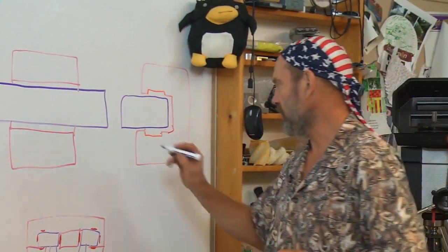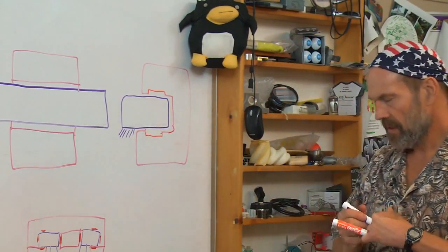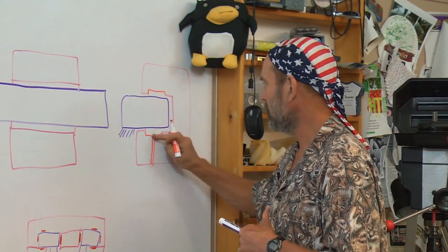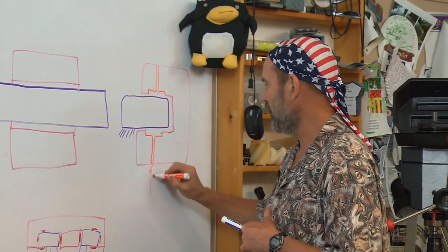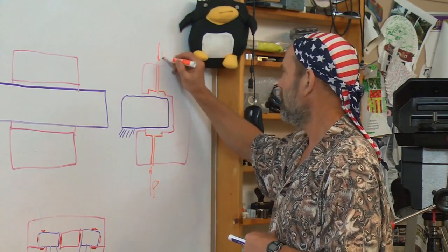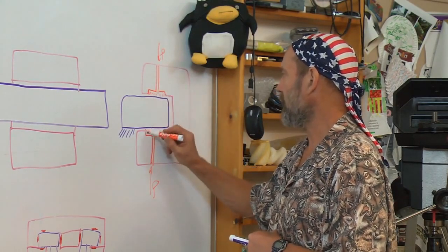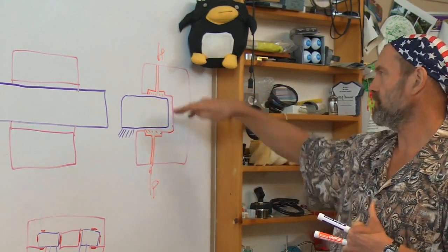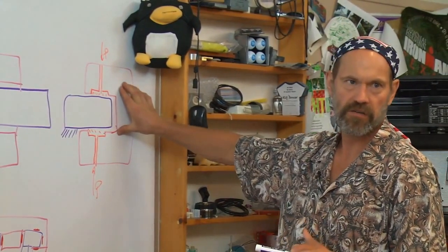And so this is not floating in air. Let me just make this like this is anchored to ground, okay? So I'm going to bring in fluid flow into that pocket. And if all I do is provide pressure from a pump, I'll have pressure applied over the area in the pocket to the top and the bottom, and force equals pressure times area. So I have the same force on the top and bottom, and this thing has no stiffness, and then just clunk. It'll go either way.